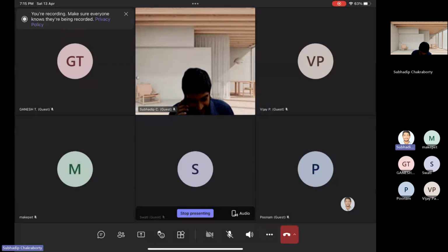Yes, so what I was telling is that for either series or shunt, you have to calculate the voltage and current parameters, the worst case scenario voltage and current, and from that you calculate the volt ampere rating.